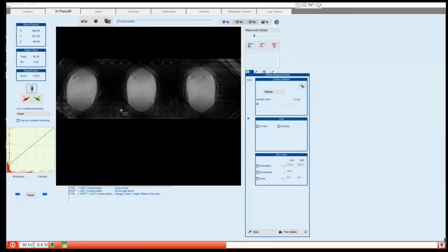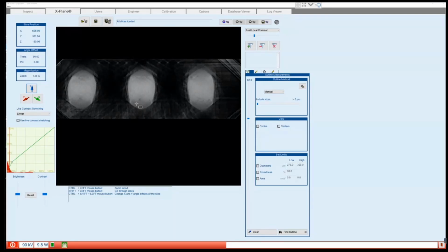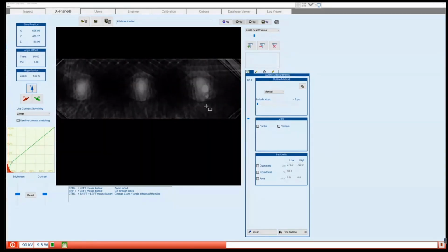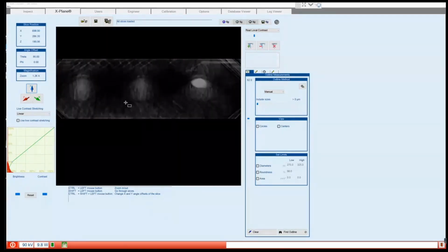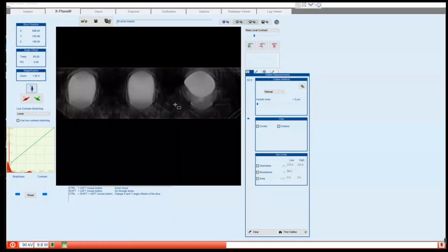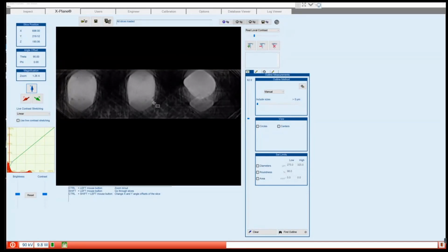Okay, so these connections look fine. We can see position of voids quite nicely. See a void quite high up in this solder joint. Some interfacial voids. Continue to go further, and you see, very clearly, a joint here on the right that looks different to the ones to the left.